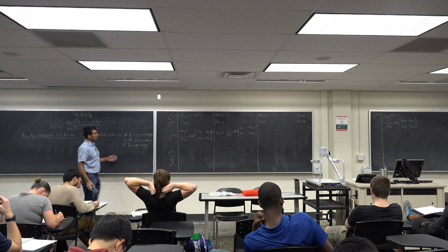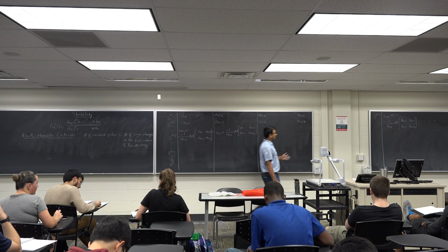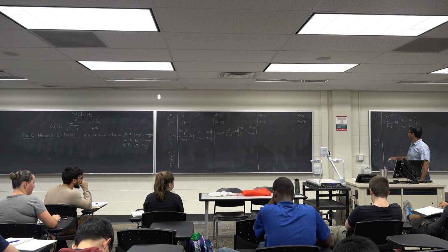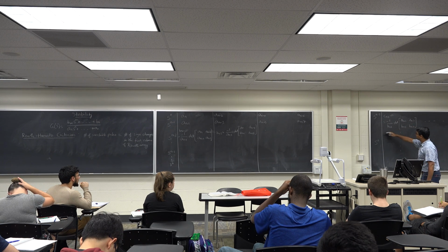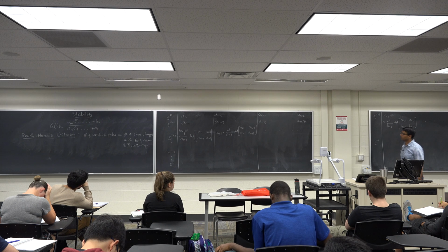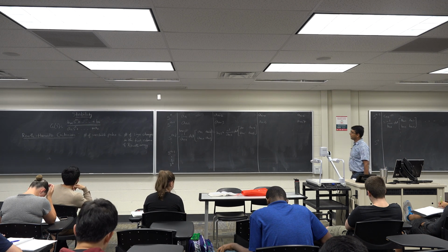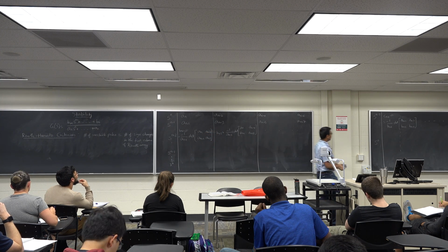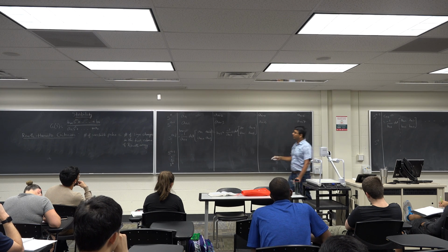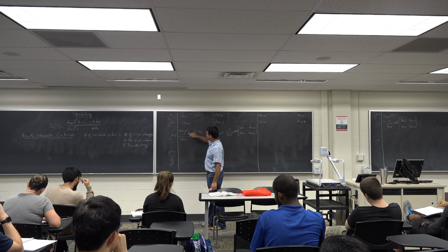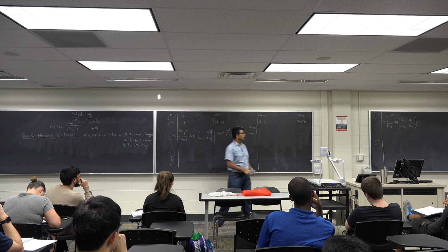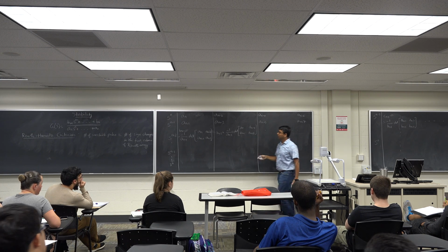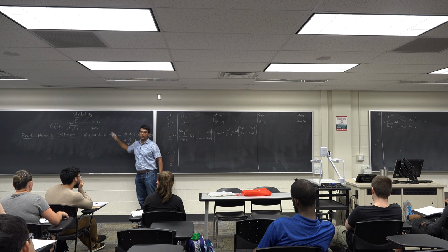So after I have constructed this entire Routh array all the way to S0, I have to construct the entire rows, then the next row, then the next row, and so on, until I reach S0. Then I look at the first column all the way up to S0 and see how many times the sign has changed. If it is positive, positive, negative, negative, negative, negative, negative all the way to S0, then there is one sign change in the first column, which means that there is one unstable pole in the transfer function G of s.